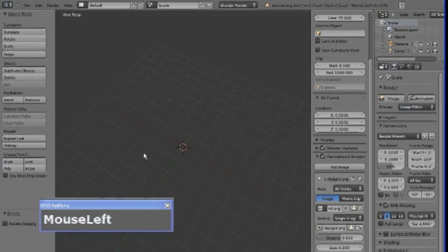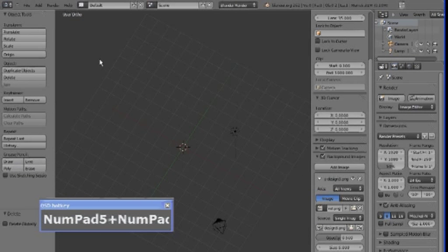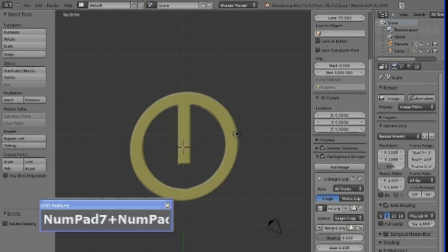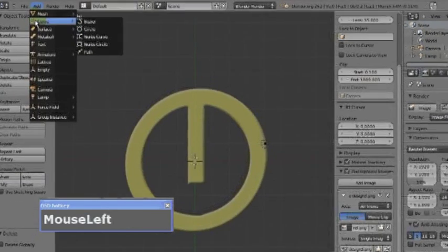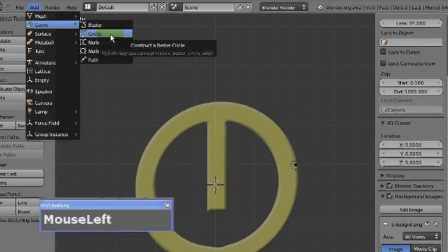Now at this stage there's no image viewable in the viewport. Reason being is you need to firstly be in orthographic view rather than perspective view. Pressing 5 on the numeric keypad will bring you into orthographic view. Next you need to look directly in an axis, so pressing 7 will give us a top down view and our image is now visible. Pressing 1 will give you the front view, 3 side view, and as soon as you go off axis your image disappears.